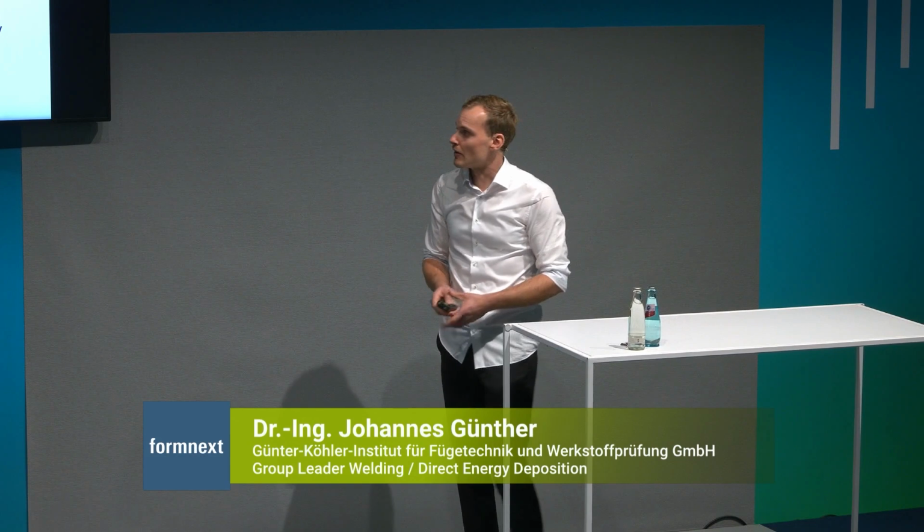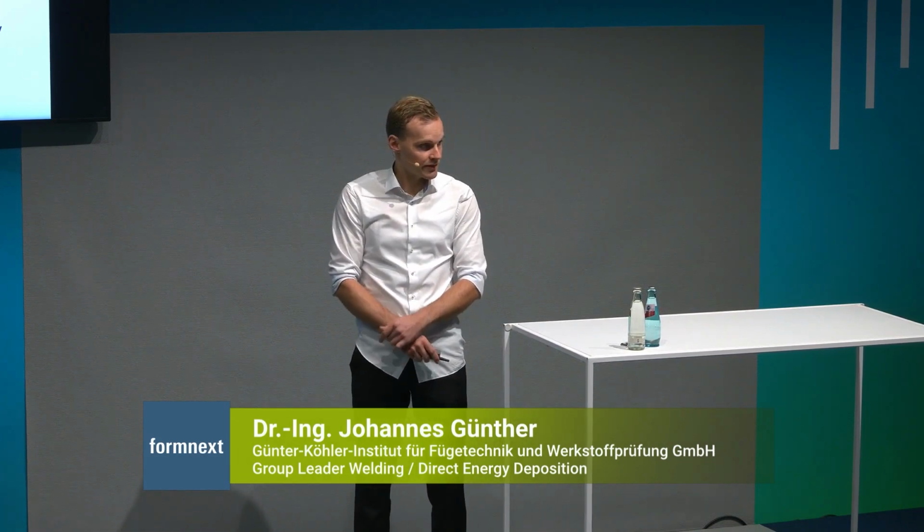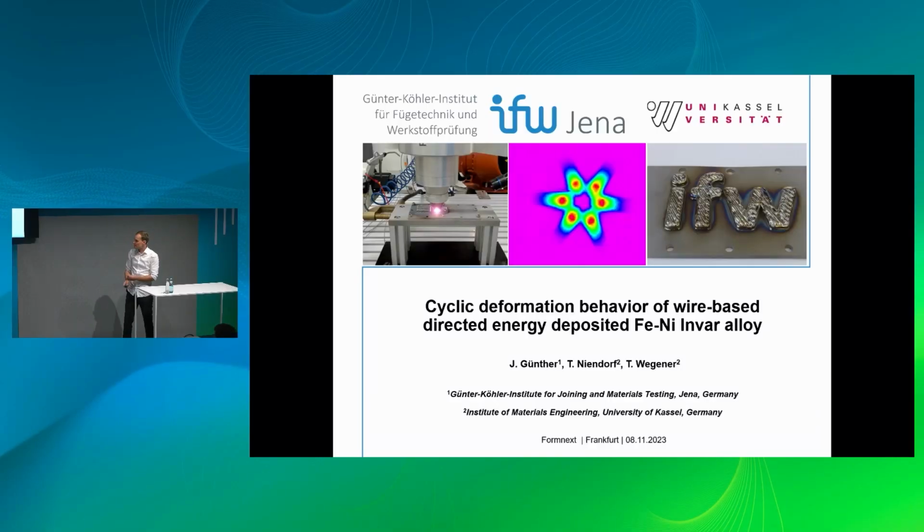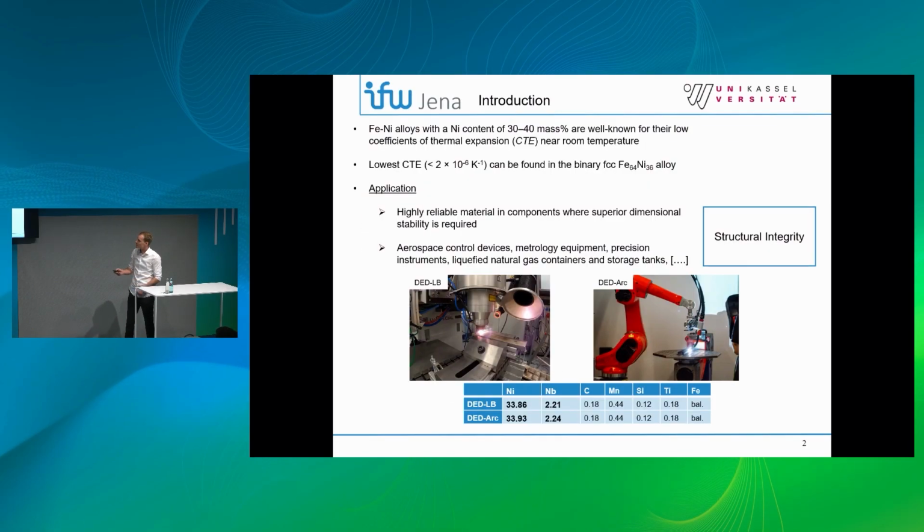Yes, I would like to present to you some aspects on the cyclic deformation behavior of Invar alloys additively manufactured by wire-based DED process. So, firstly, iron and nickel-based Invar alloys are a group of functional materials that exhibit a very low coefficient of thermal expansion. Especially the binary iron-nickel alloy containing 36% of nickel shows the lowest CTE values.